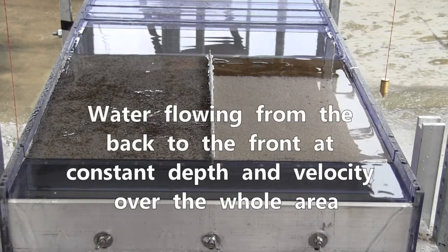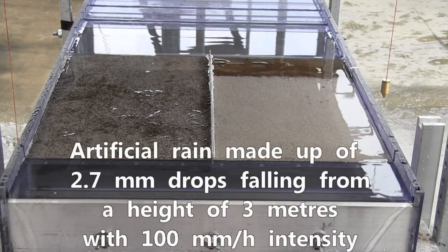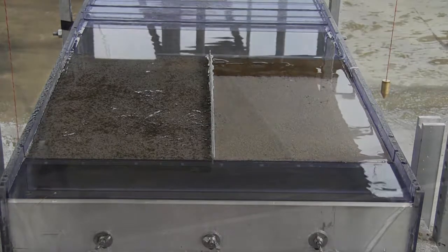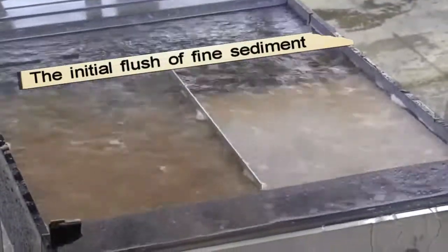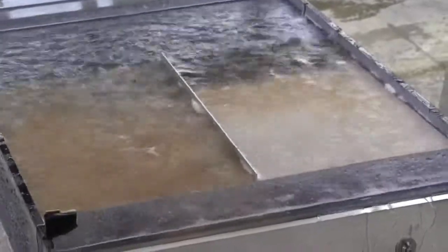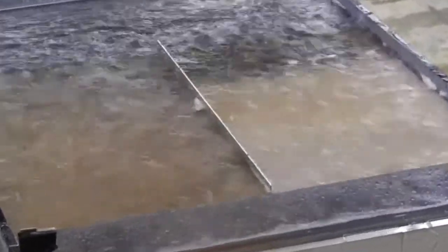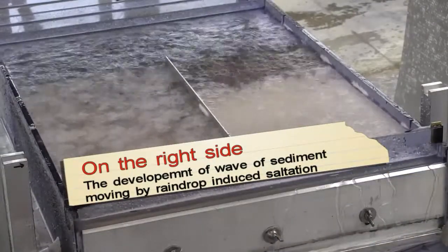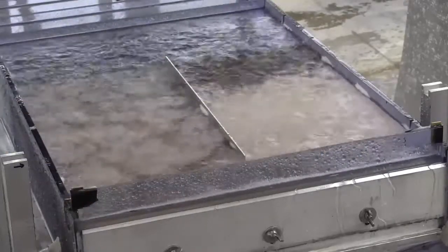Water flows from the back to the front at constant depth and velocity over the whole area, and we apply rain using 2.7mm drops at 100mm per hour intensity. Initially we get a flush of fine sediment, which in this case will disappear fairly quickly. And then we get the development, on the right hand side, of a wave of sediment moving across the surface by raindrop induced saltation.